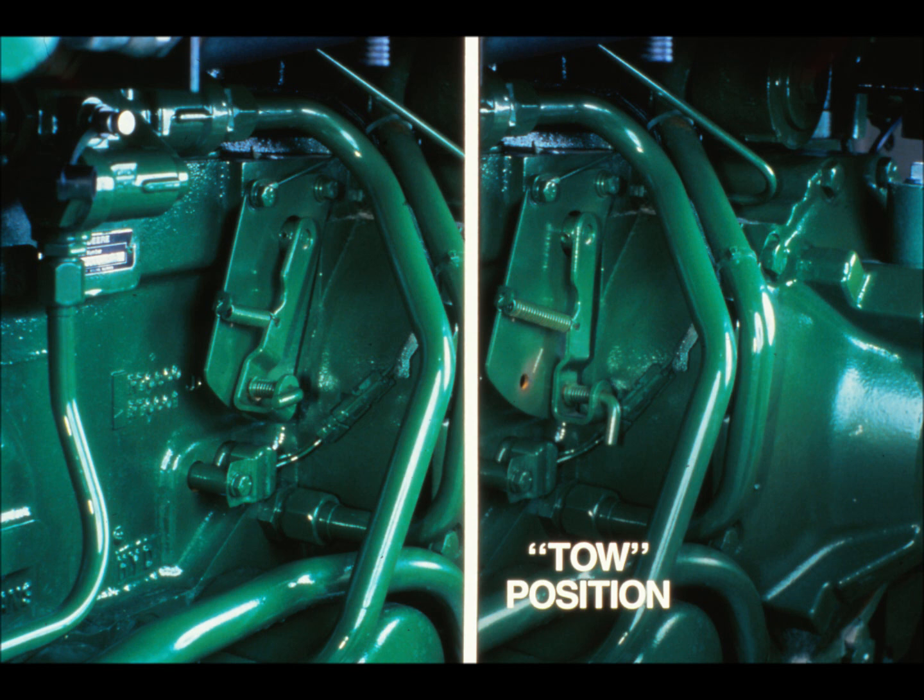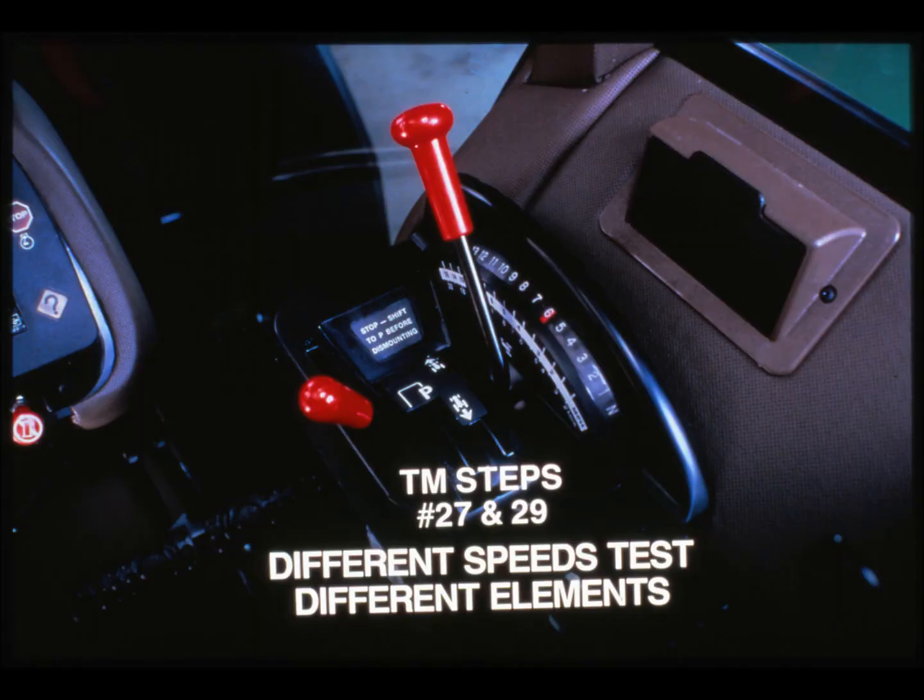The next few tests involve operating the transmission. Make sure the transmission has been placed in the tow position before doing these tests. Steps 27 and 29 show you how to test the clutch and brake circuits in the power shift transmission for leakage. The procedure tells you what speed position will check which transmission element.